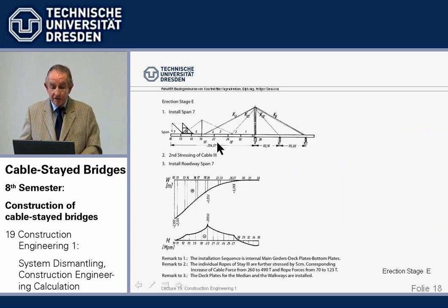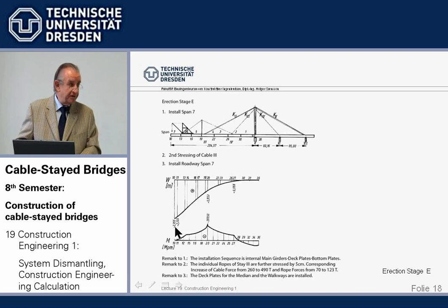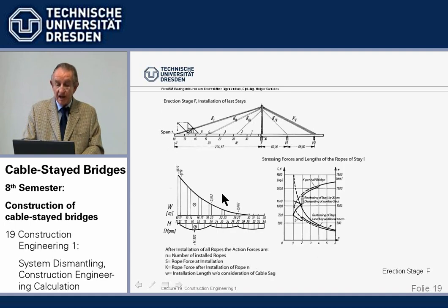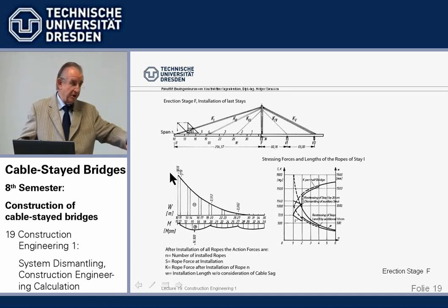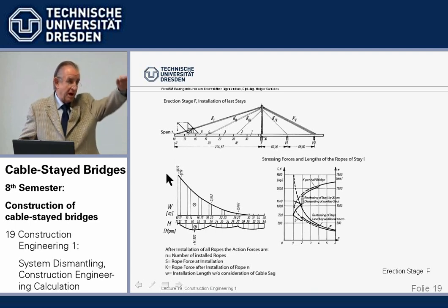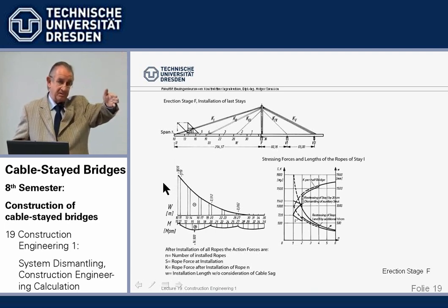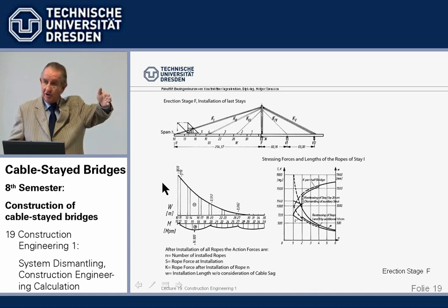Okay, it goes on. We have the auxiliary stay, and we have a cantilever, here a long cantilever, which again now we go down 2.3 meters just before closure. And the next one, we have now installed the most forward cable, then it goes up by 1.3. So we have a movement from 2.6 meters down to 1.3 meter up of the tip by just installing the cable.